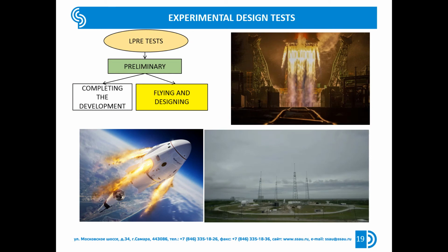Flight and development testing of prototype LPREs is usually carried out after successful completion of bench tests as part of the engine unit. The main purpose of flight development testing is to verify and confirm the performance of the LPRE and to check its performance against the specifications under actual operating conditions. In the course of flight and development testing, additional modifications can be made to the liquid propellant rocket engine.